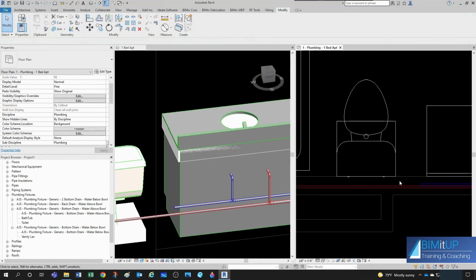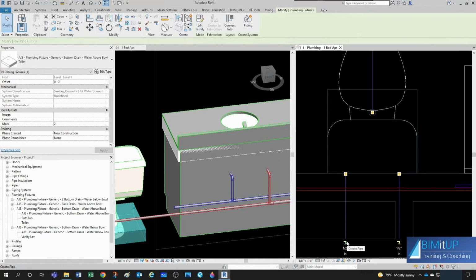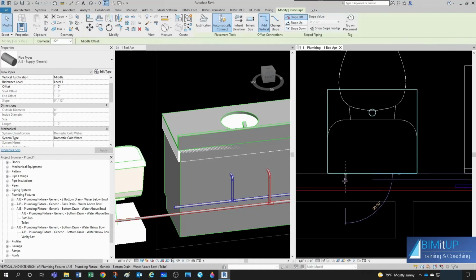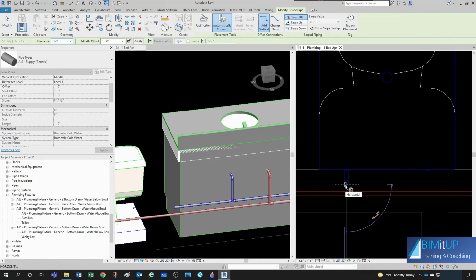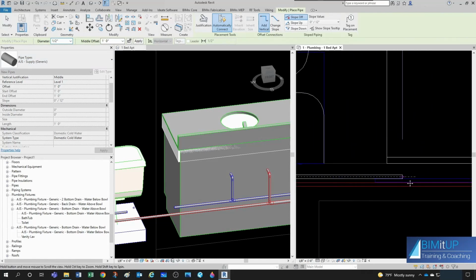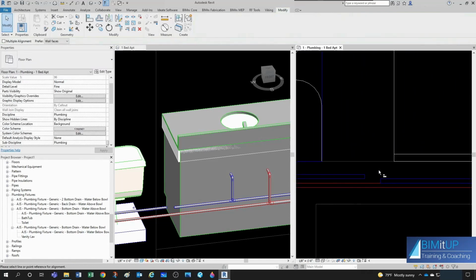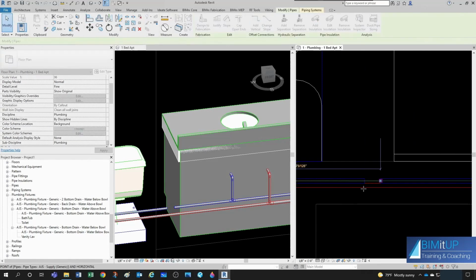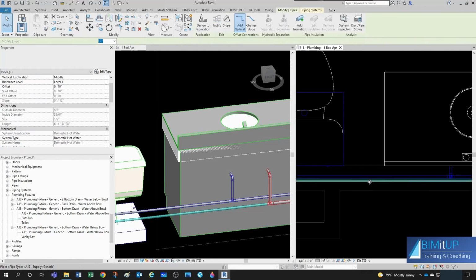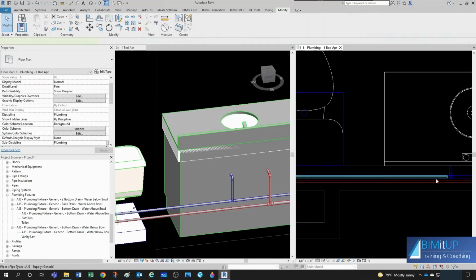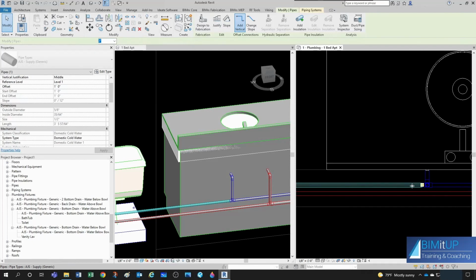And in a similar way, I can come, well, this was my toilet, right? So I want my cold water connection coming out like this. And we know that our, well, actually this one's already at 1 foot, so these two pipes should be able to connect as long as they're aligned, right? So you can do this and then this. Okay, let's separate the hot water a little bit and then bring our cold water closer to the stop valve.